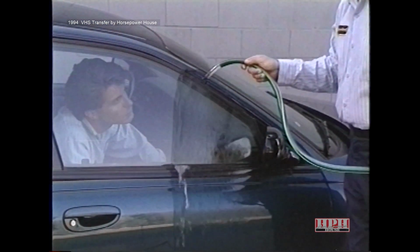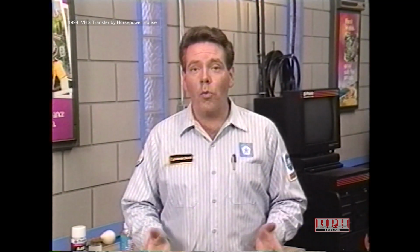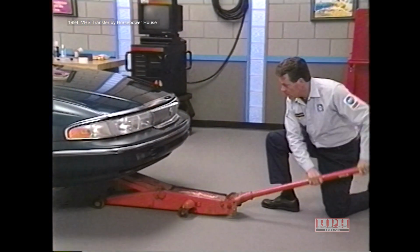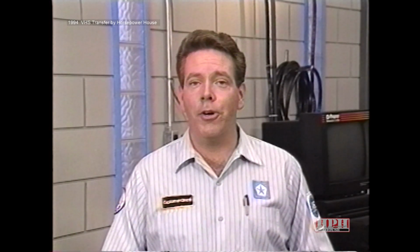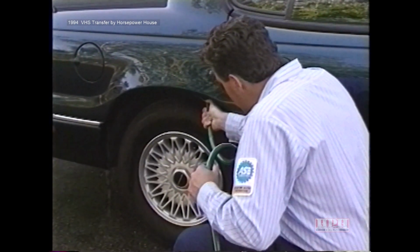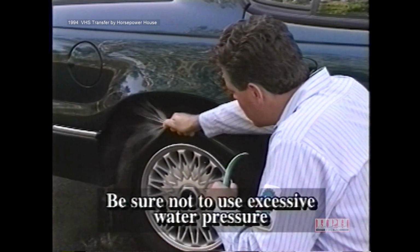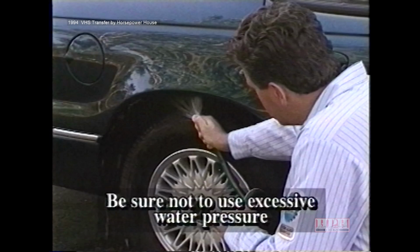inside of the vehicle. If a leak occurs under certain conditions, such as when parked on an incline or while turning, you'll need to hoist the appropriate side of the vehicle to simulate the condition as closely as possible. And if a leak occurs under highway conditions, try using a fan spray of water directed at the vehicle in a direction comparable to actual conditions. But be sure not to use excessive water pressure. Even a good seal can leak if the pressure is too high.